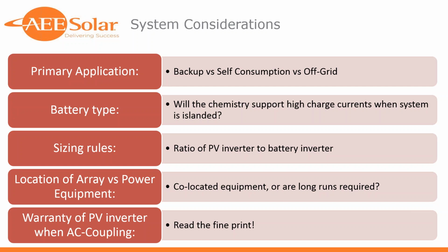Sometimes it is better off to take that PV inverter off the wall, install a charge controller, rewire the array, or do a high voltage charge controller, and maybe you've got a PV inverter for your next project, or weekend cabin, etc.